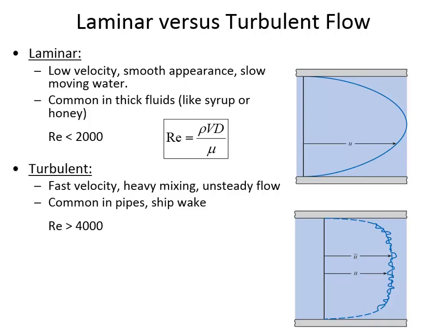Very good. So viscosity divided by density gives you kinematic viscosity. And the reason why I bring it up right now is that's the formula for Reynolds number. You can say that the Reynolds number is the density, velocity, diameter divided by viscosity. Or you can say it is velocity times diameter divided by the kinematic viscosity. And that's a little bit simpler. It's got one less variable there.